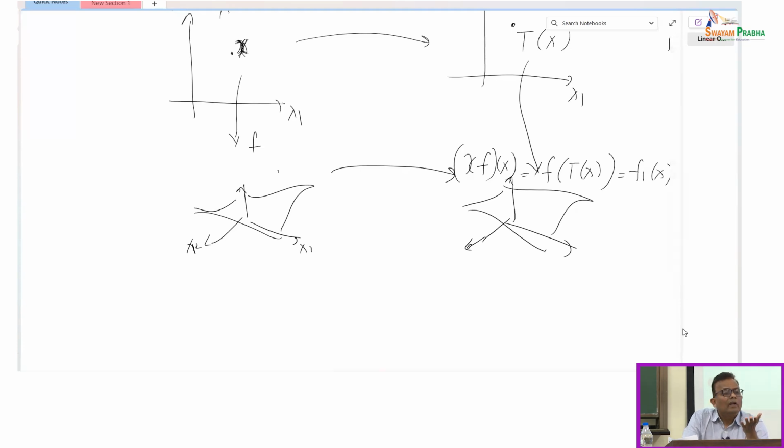I mean, even for finite dimensional linear systems, you can actually do control design based on the spectrum. Of course, you don't do that because we use optimization-based methods, LMIs and things. But underneath, if you open them up, you will see that eigenvalues and eigenvectors are effectively used whenever you're solving either Lyapunov equations or Riccati equations. Okay.